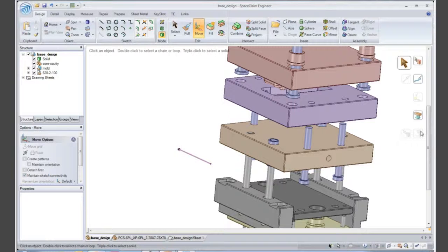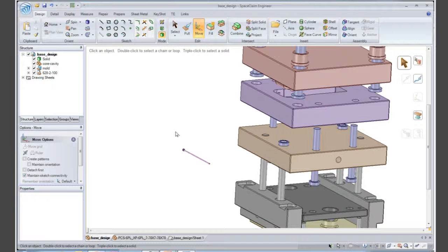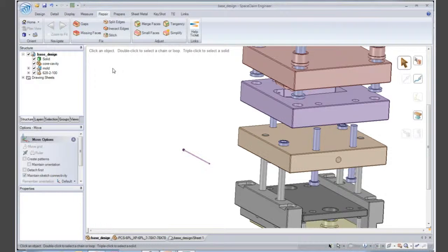So one question is, how do you deal with real-world STEP files with molding? A question basically on cleaning models before you work with them. Now, it sounds like a few of you have been burned in the past, and actually I have as well. A lot of times when you get IGES files or STEP files in, they can be really dirty. So we have this repair tool that's specifically designed for that. The repair capabilities allow you to repair models and bring them back into a 3D solid if you start to get just surface geometry in, basically surfaces with zero thickness.